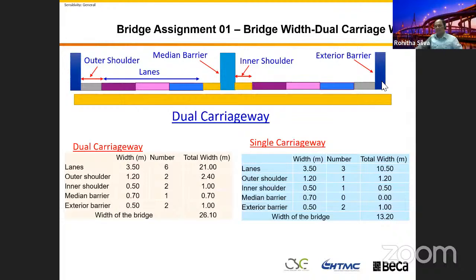I think I gave you a lot of bridge drawings before. For the deck, I put 0.5. That figure also changes a little depending on the shape and urban design and stuff like that. The 0.5 is reasonable for concept design. There are 2 edge barriers, or exterior barriers, you can name it either way. Then you calculate this together.